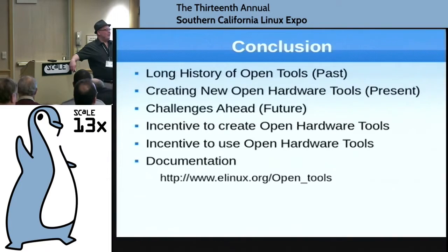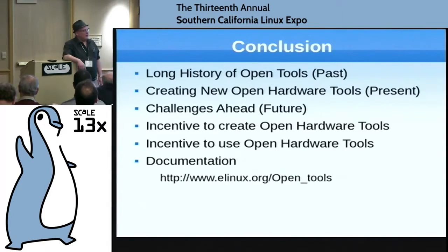Yes, you can. They're out of stock at the moment, but you can email them directly. I think they're planning to do a build of them. Although it is primarily geared towards DVI, it works with HDMI as well. It does not support the audio from HDMI, but you can look at it and debug HDMI and DVI. And it's got the EEPROM on there, so you can program your own EDID and pretend to be whatever you need to be.